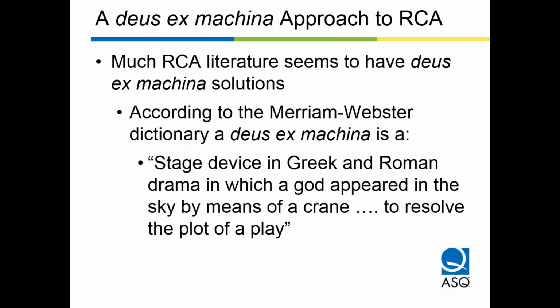The consultant's not alone in neglecting to mention the need to actually look at the part. I've read a lot of the literature, and a lot of the literature seems to explain the team should sit together and use quality tools to find the cause of the failure. Not a bad idea itself, but they fail to mention what Dorian Shainin said: talk to the parts. They're smarter than engineers. We need teams, we need tools during root cause analysis. In my view, the most important team member is actually the defective part. And I will say, if available.